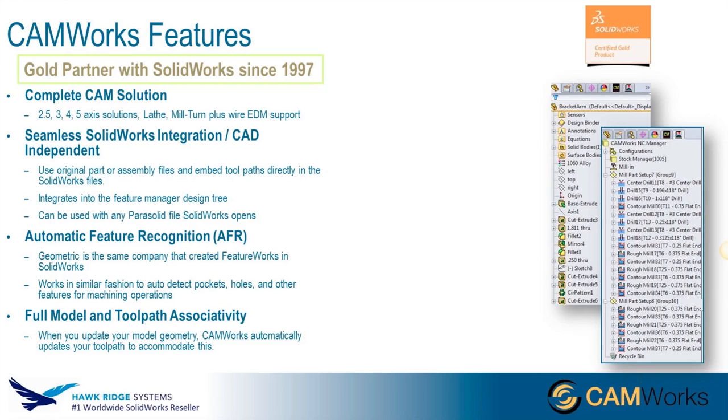And the other beautiful thing is if you do make a change to the model, I know people go through ECOs and things like that, change requests in their systems and their companies. You've got a revision change. Okay, well, how does that affect the program? Basically, in CAMWorks, there's no having to export anything. We're working right inside the SOLIDWORKS model. The toolpath lives in the model. If the engineer goes and changes the model, he won't see CAM because he doesn't have the add-in loaded. But as soon as the programmer brings it back up, you'll see the toolpath will actually prompt you to update, and you'll see some of that later on.